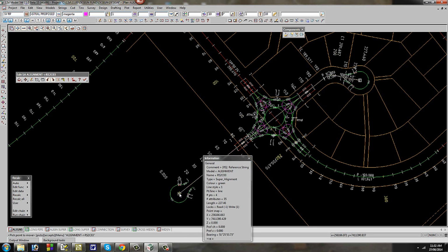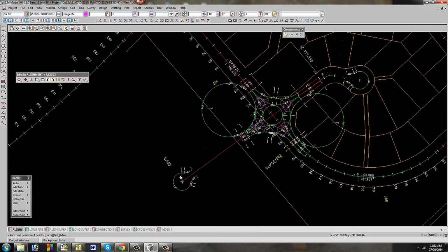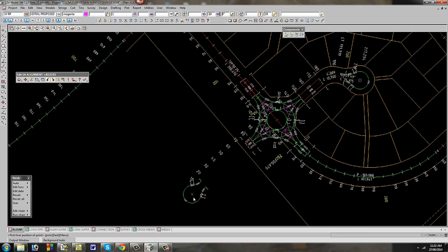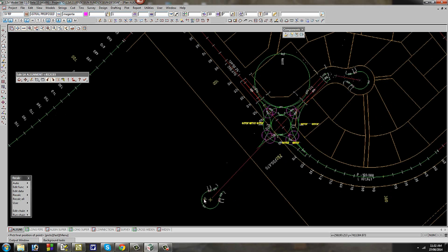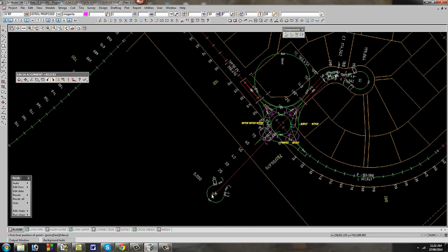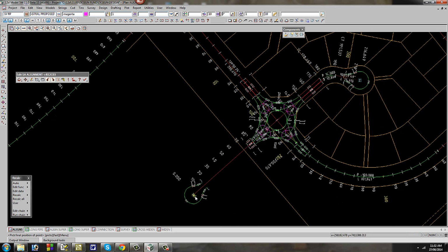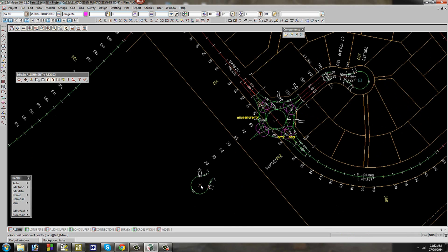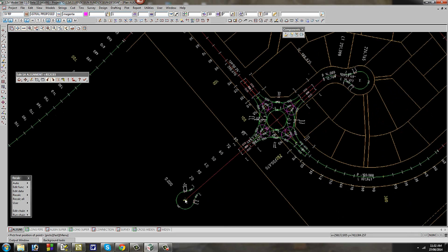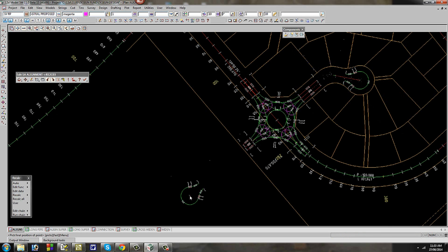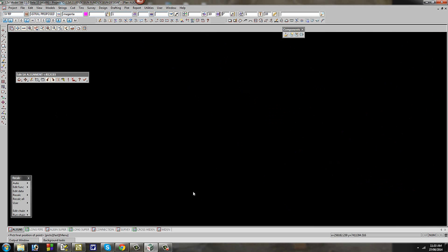If I select move, grab my IP point, and I can adjust. As I adjust this around, it's automatically updating every component or super alignment that's referenced to that string without the need of a chain to do so. This is a feature that's available for every alignment string, and it will search through and find strings that are referenced to it and automatically update them.